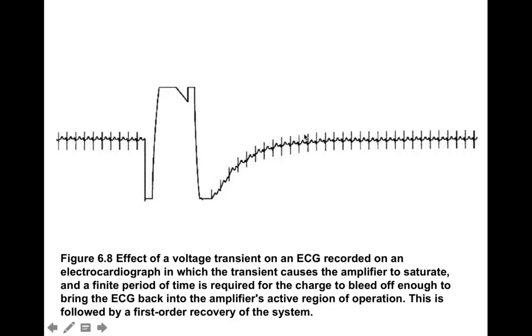The problem with obviously making the amplifier less sensitive, so that you are using some kind of voltage divider prior to input, is that while you may reduce the input voltage of your transient, you also reduce the input voltage of your actual signal. So there's a sensitivity trade-off there: if you amplify too much, you get these transients being greatly amplified. If you don't amplify enough, you can't resolve enough of your actual signal.